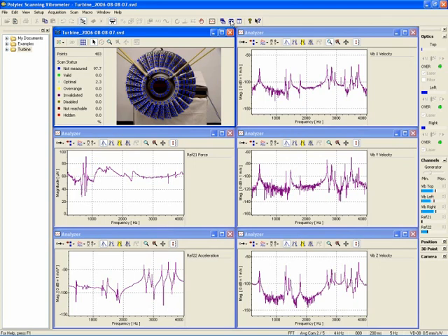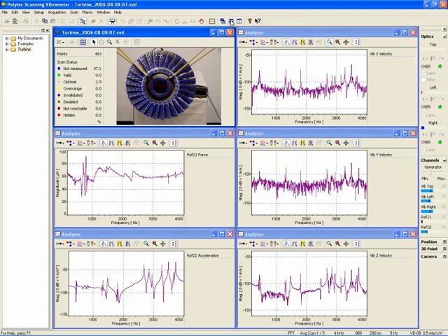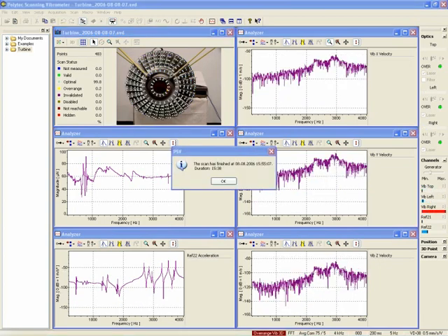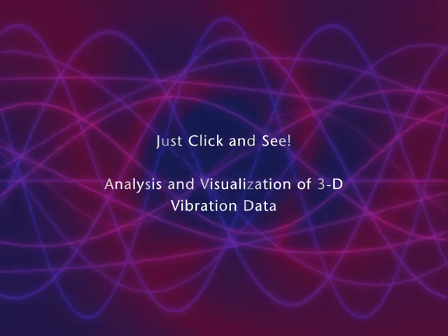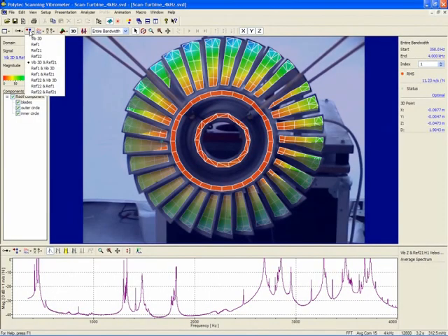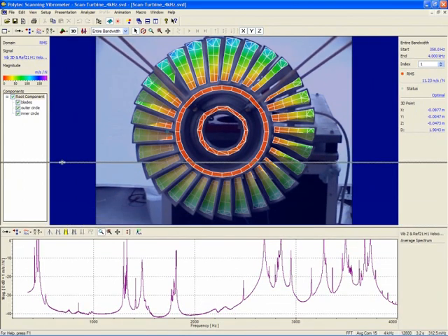During the scan, time traces and frequency spectra are displayed for all vibrometer heads and also for external reference signals. Depending on the measurement type, time domain or spectral data is acquired for each sample point and can be animated temporally or as a phase-synchronous deflection shape.